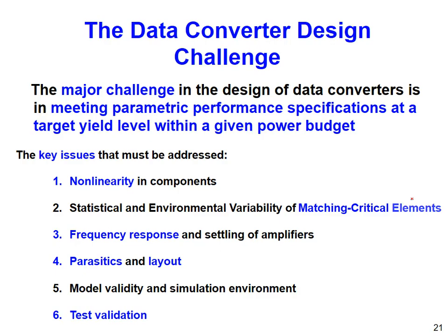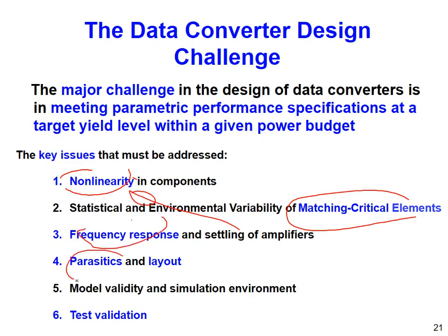How many parameters do you need to face for data converters? A lot of them. For example, nonlinearity. To get good enough accuracy or linearity, you need to match critical devices on the chip, right? And how fast you can operate. You also need to pay attention because it is strongly related to the parasitics of your layout.